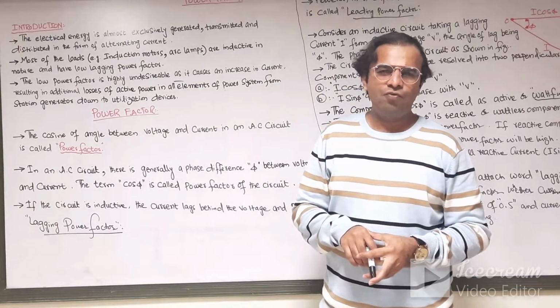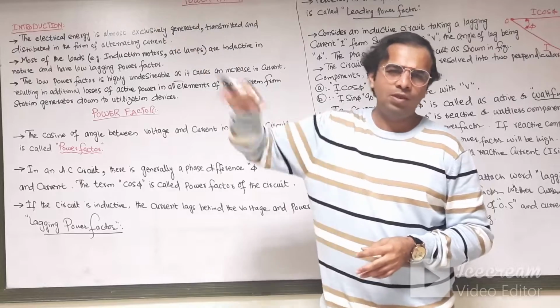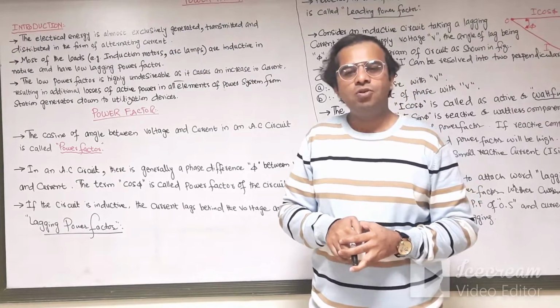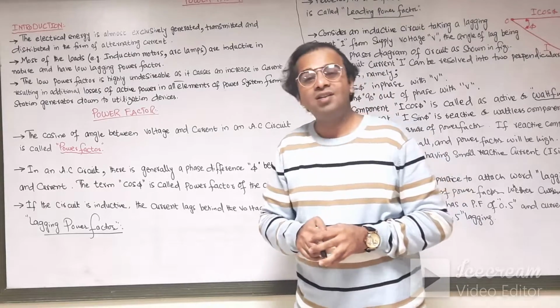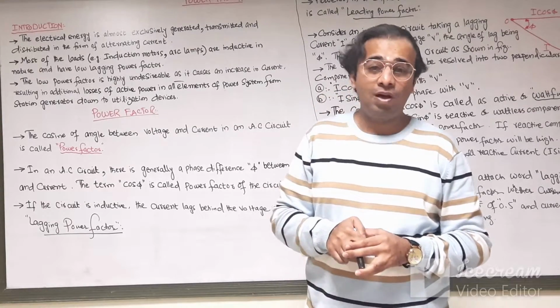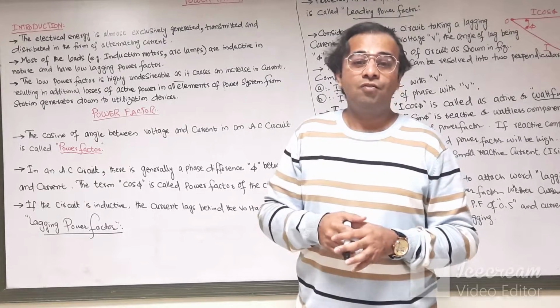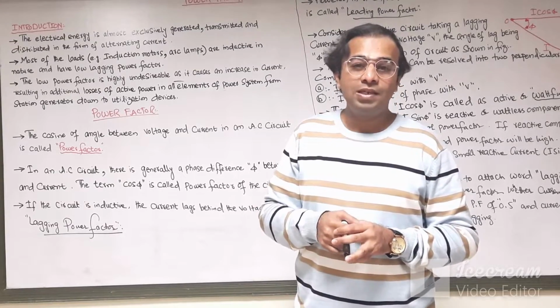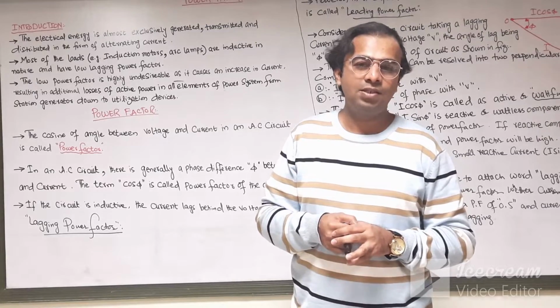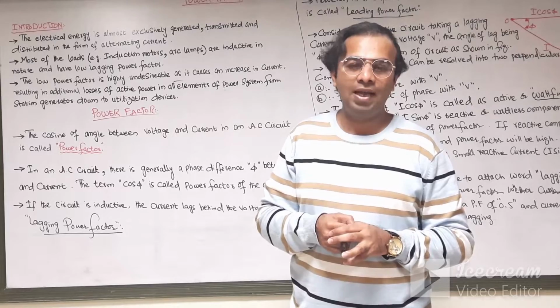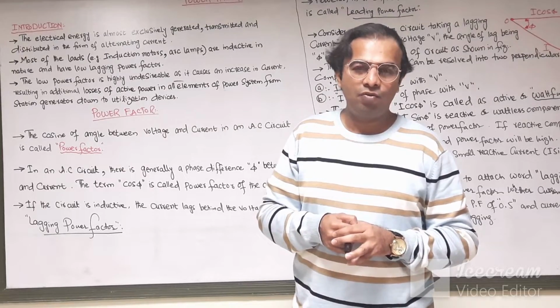If the power factor is not maintained from the generating station side up to the utilization side, it causes additional power loss in our system, so our consumed power will be lost, and obviously the consumer at the utilization point will pay a higher electricity bill and will be penalized because of the low lagging power factor.